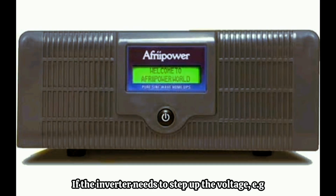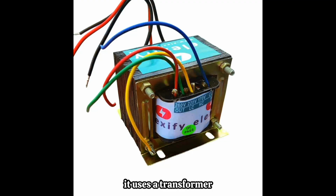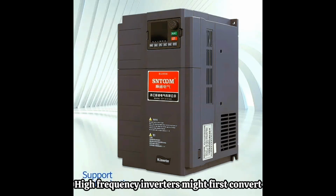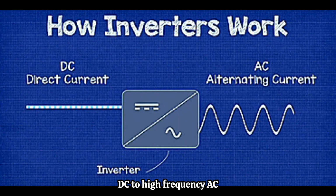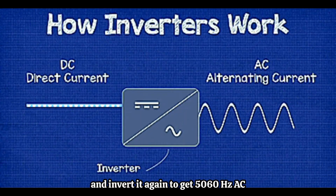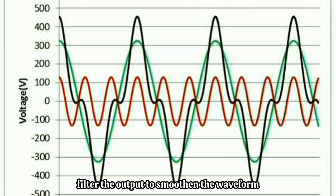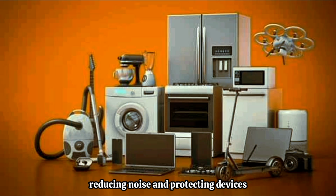If the inverter needs to step up the voltage, e.g., from 12V DC to 230V AC, it uses a transformer. High-frequency inverters might first convert DC to high-frequency AC, step it up, then rectify and invert it again to get 50-60 Hz AC. Capacitors and inductors are then used to filter the output to smoothen the waveform, reducing noise and protecting devices.